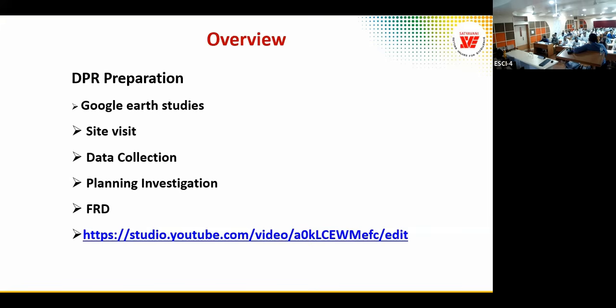RQD is the one which indicates the real state of the rock in the site, even before we do excavation. If RQD is not done adequately, like what we did, the mistake we made was that we didn't do RQD in all 20 boreholes. We did RQD in only 3 boreholes. So it was not representative, because it was all rock.